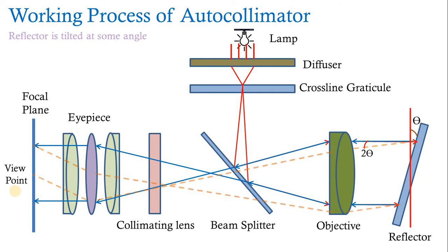It responds only to reflector tilt, that is, not lateral displacement of a reflector. If there is a deflection at the surface, then that can be responded to by this reflector. This is independent of separation between the reflector and the autocollimator, assuming no atmospheric disturbance and the use of a perfectly flat reflector. So there we are getting this measurement of angle 2 theta, that is x.